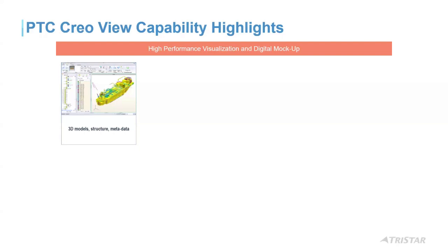You can do this. You can set up Windchill, you can set up Creo to create these viewables in a graphical format only. So it'll strip out all of the geometry details, all of the metadata, and only send somebody something to view, something to look at, to spin and rotate, zoom in and zoom out, just to get enough detail that they need. So there are ways of protecting your intellectual property with Creo View.